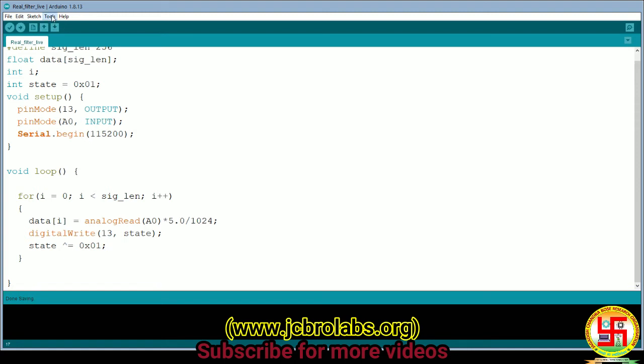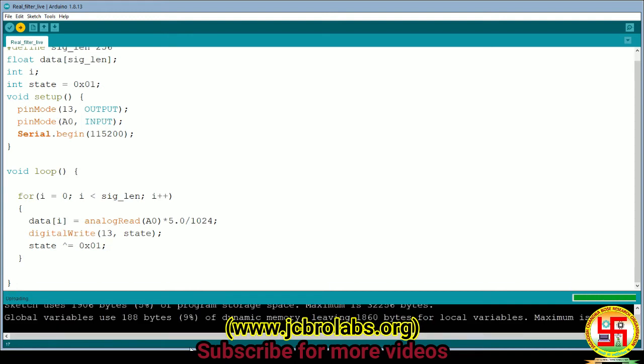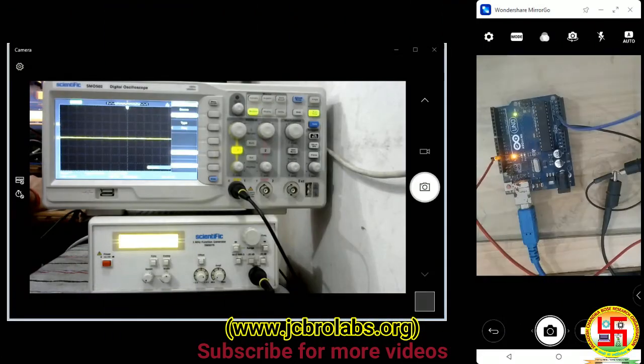Okay, so let's compile and upload it. Our Arduino is connected to COM8. Okay, so it's compiling. Hope we don't get any error. Okay, and we are not getting any data on the CRO as well. Let's see. Okay, we are not getting any data. That means this pin number 13 is not toggling, I think.